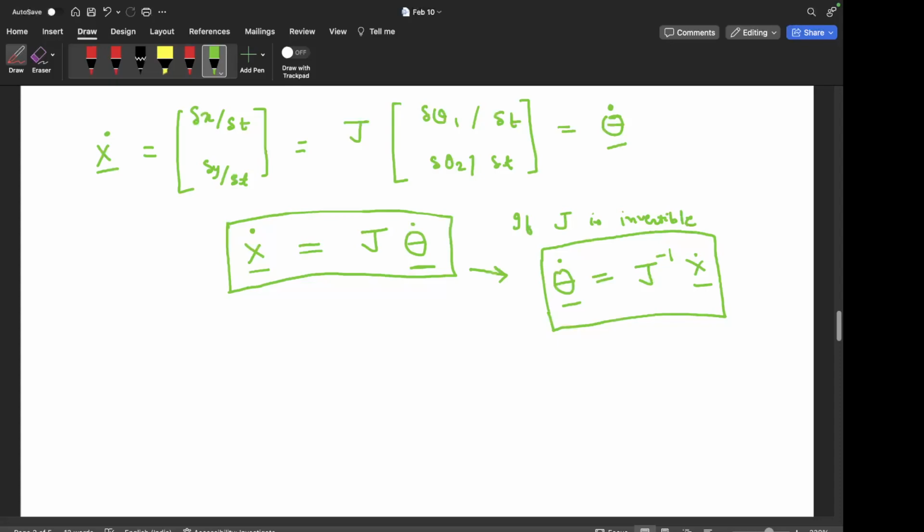So let's say this is just a 2 link manipulator. Let's say you have a 3 link or 6 degree of freedom manipulator, complex, or not even manipulators, other complex robotic systems. Let's say a wheeled robot with a manipulator on top, whatever be the complexity of the system. Once you have the Jacobian matrix, you need not do the kinematics of the system link by link, which is prone to mistakes and difficult to program also.